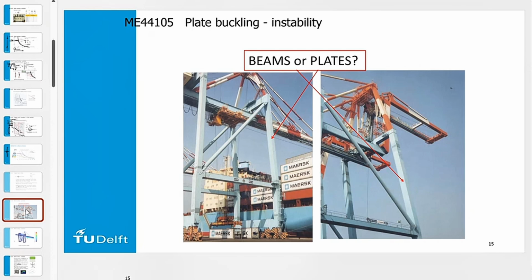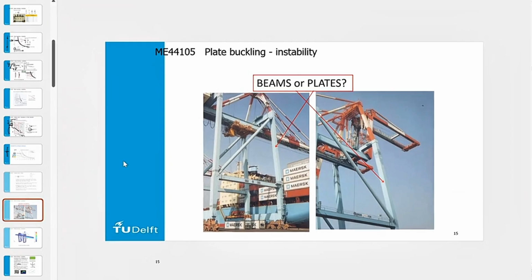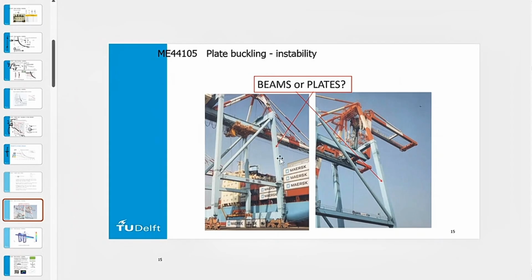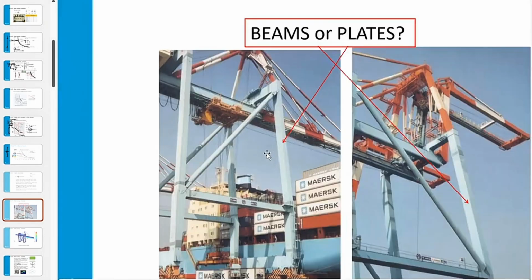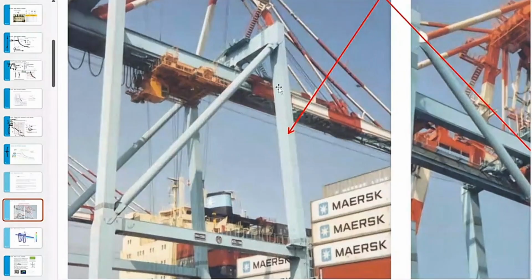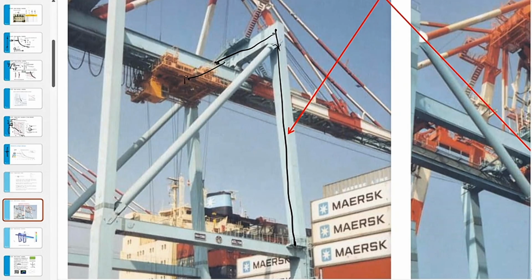If we take a beam model and take into account the buckling analysis, we can say, okay, as long as we can recognize something which is like a beam, like this one here, then we are fine. So initially we can do a buckling analysis with the beam elements, but be aware of what happens in here. In general, these are fixed boxes if the design is well.